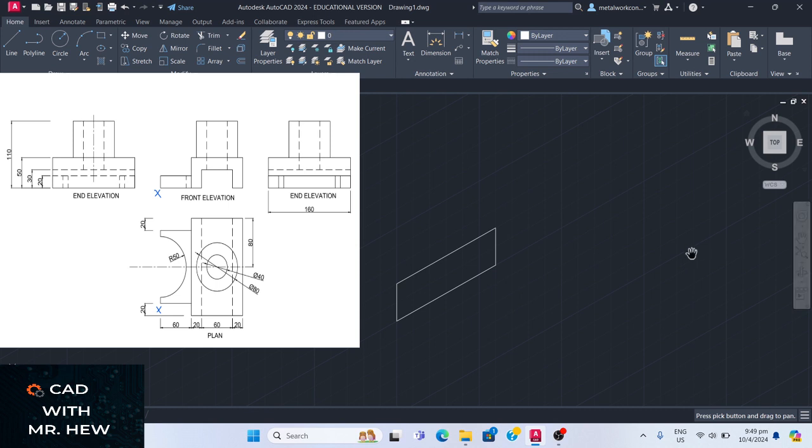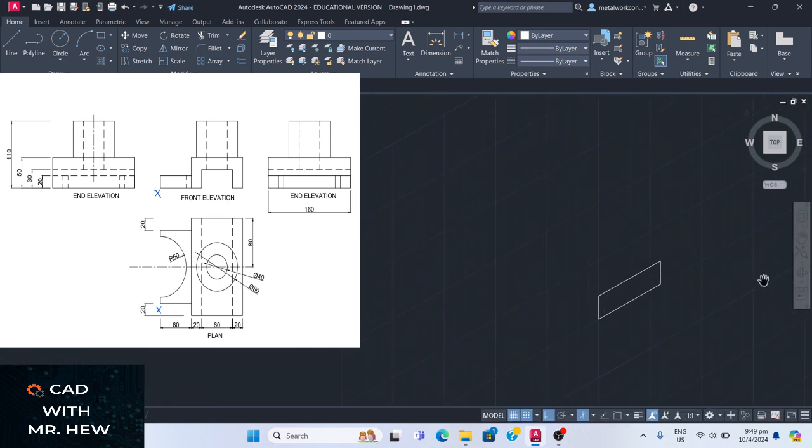Let us center the drawing. Now we're going to change our isoplane so that you can see the left side. We go line, turn on object snap, which is this icon down here, fixed to that corner.